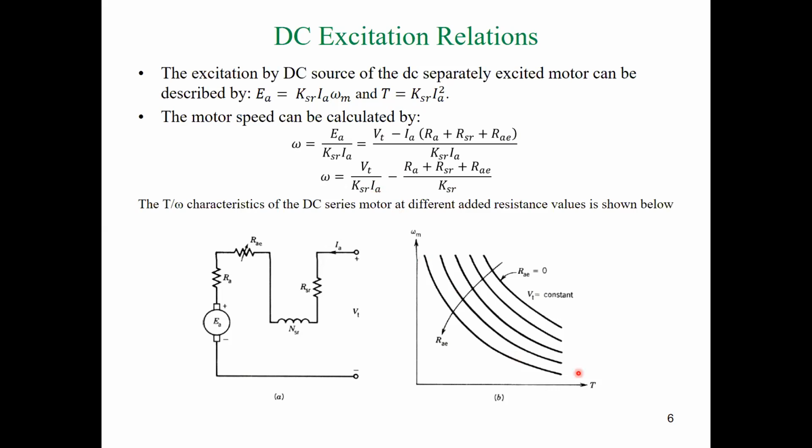It could be found that we have the same characteristic here like in series DC motor. So these are the characteristics of series DC motor. And as you can see, by changing the value of the rheostat, we can go in this direction with the characteristics. So we can make speed control by means of changing our rheostats. So this is the performance characteristic of DC series motor.